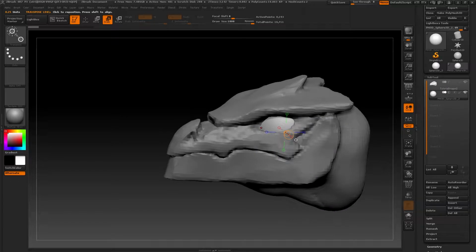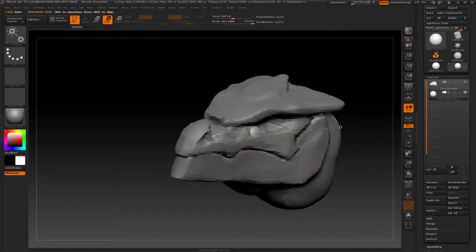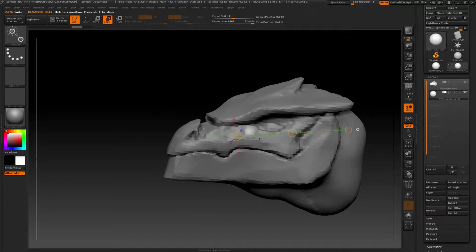At the top you have these three tools: Move, Scale and Rotate. Select Rotate and you get an orange line with three orange balls. All you have to do is click where you want and drag to create the orange line. To scale, you need to place your cursor above the third orange ball and a red circle will appear. Click inside the red circle and move the mouse to the beginning of the orange line to scale. Repeat this action as many times as you need until you get the size you need.